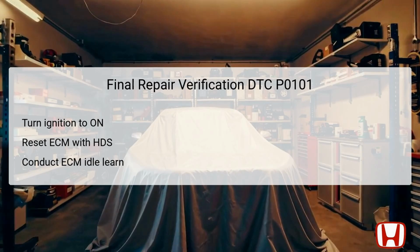Finally, a test drive in conditions that reflect the previously recorded freeze data parameters is vital. Climbing through the engine speed and monitoring the vehicle speed, MAP sensor, and TP sensor readings, while observing the OBD status for DTC P0101 will determine if the problem has truly been resolved. This last step not only verifies the successful repair, but also confirms that the vehicle is functioning optimally.